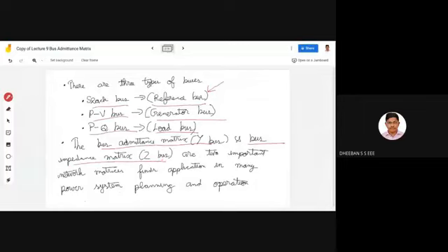If you form the Y-bus and the Z-bus matrix, it is very easy for you to use the computational methodologies which you are going to see in the second and third units. This is the initial step that you have to consider for the computational analysis of the power system network.